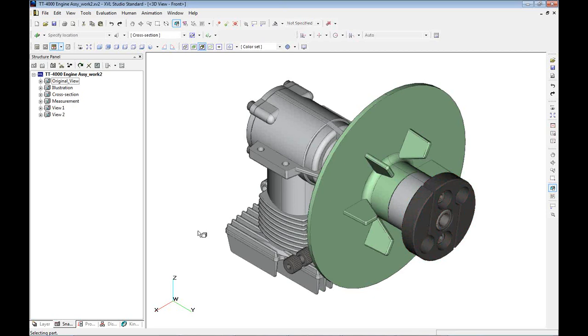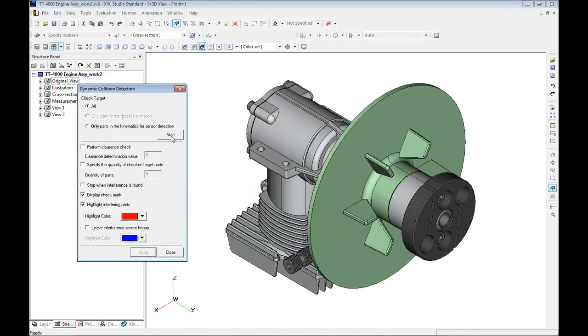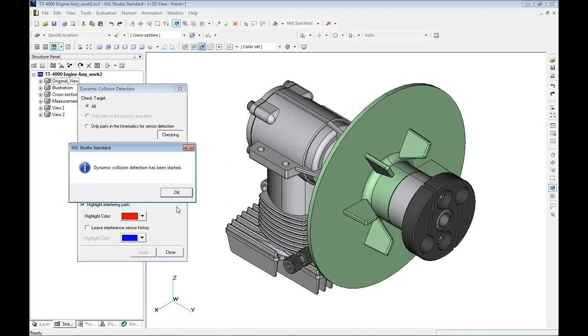Gary has another question. Can it detect clearance issues where a bolt cannot be installed due to an adjacent part? Yeah. So the question, I'm repeating the question for Masaru's benefit because I've got the headset on, was about detecting clearance issues, so if the part cannot be installed due to an adjacent part. Maybe you should turn on the dynamic clearance, and we can show what happens. So yeah, within the collaboration suite, you can do what we call dynamic checking here.